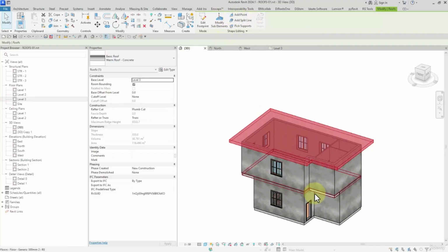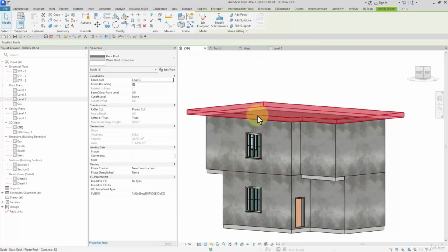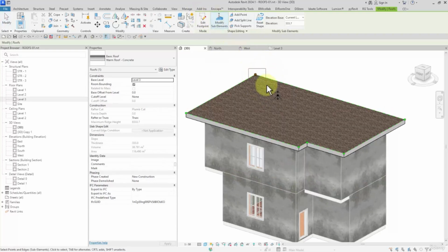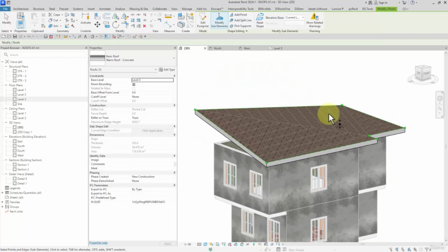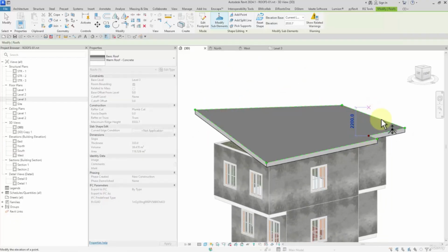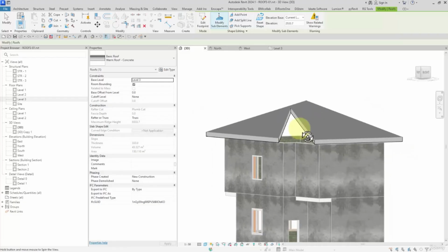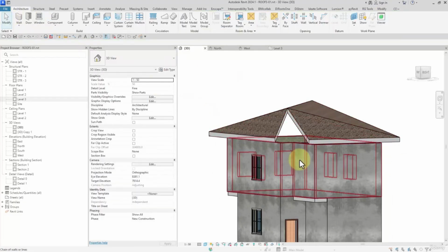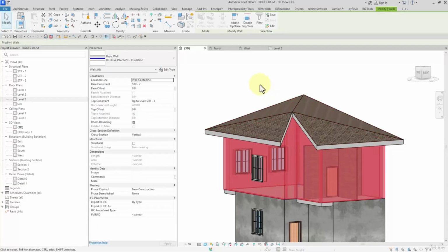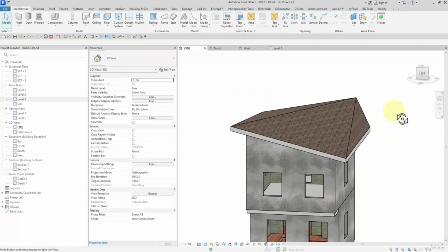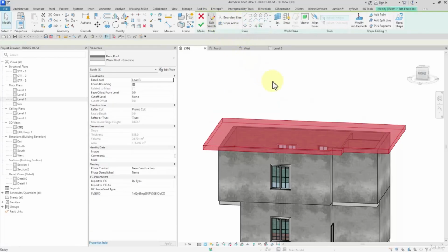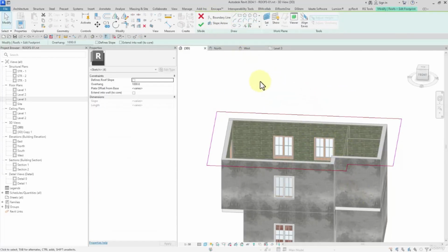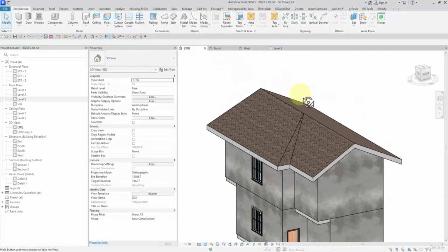Anyway, if you removed the slope like this and you had it flat, then you'll have some shape editing options that we talked about in floors. No, they are the same. Again, we can add some points manually. Watch this. We can consider the slope, we can draw split lines like this way. We can select the walls and then attach them to the roof and model such a roof for them. Again, we can reset it to its default mode like this way, and then define slopes from scratch.